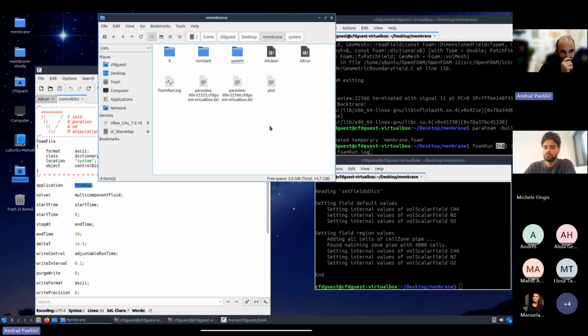So usually for OpenFOAM, let's say we can use the conditions that we want to drop our residuals to the power of -3. You can also use harsher conditions. That always depends on your system itself. Sometimes you don't want to follow just residuals of the velocity or the pressure and so on, but some more physical thing.